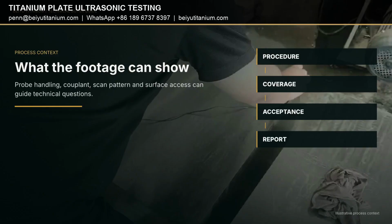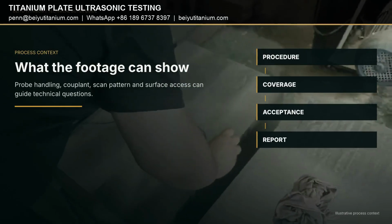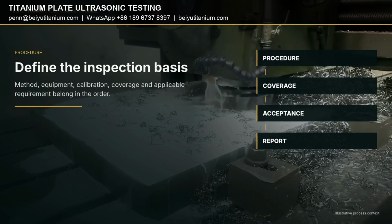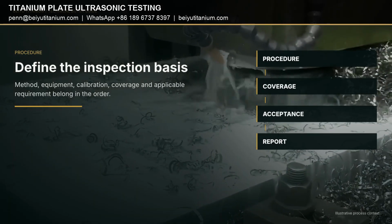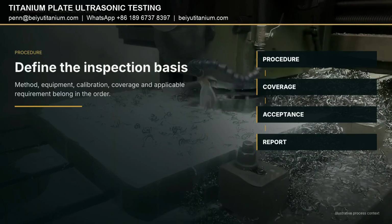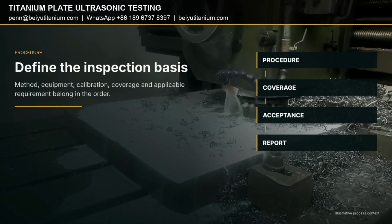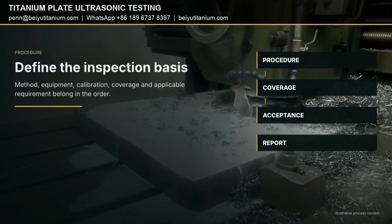Calibration and sensitivity are also part of the inspection system. The equipment, probe, reference standard, or calibration block, scan settings, and verification checks determine how the examination is performed. A screen image without that context cannot be compared with another supplier's result.